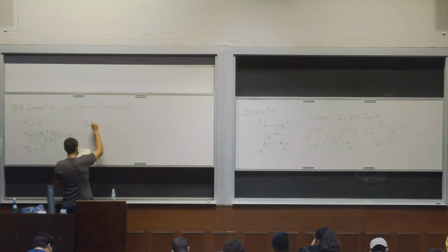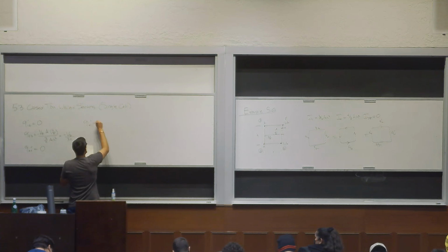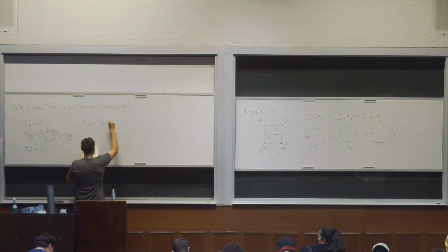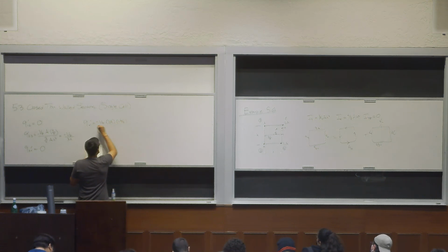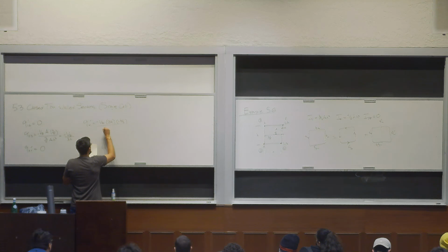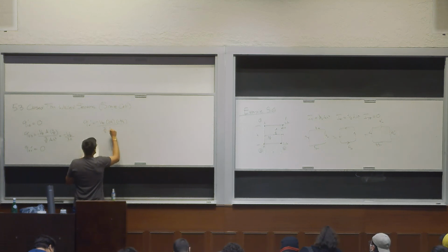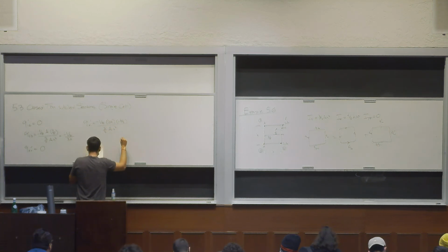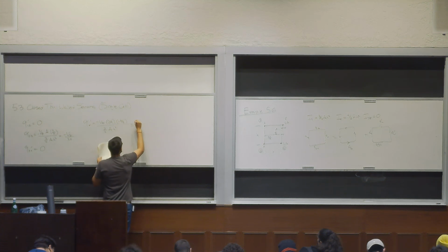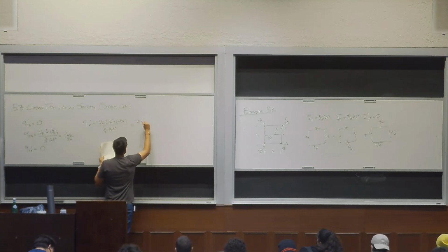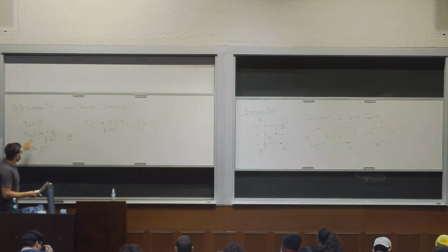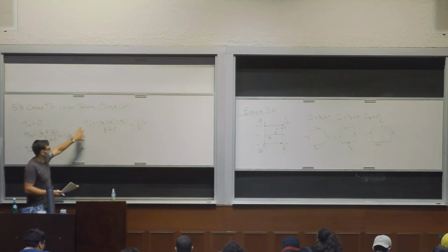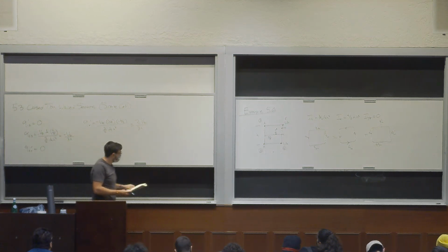Q41 prime is negative VZ times 2A times negative H over 2, over 3/2 AH squared, equals 2 VZ over 3H. Okay? So we have only these 2 shear flows that are non-zero. So we're halfway done.